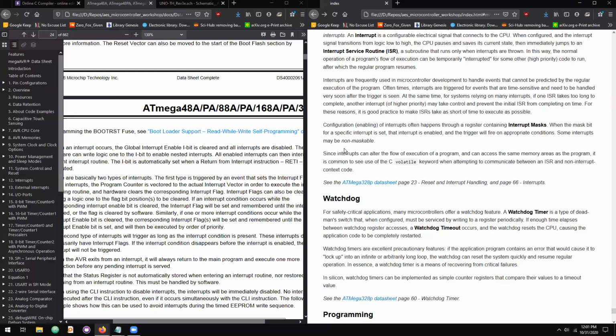And in that case, the variable's value will be changing without your regular program accessing it. And that's a condition where we would need to use the volatile keyword to make sure that that variable isn't optimized out or cached, to make sure that the regular executing program will be able to detect the variable value change that the interrupt has commanded.